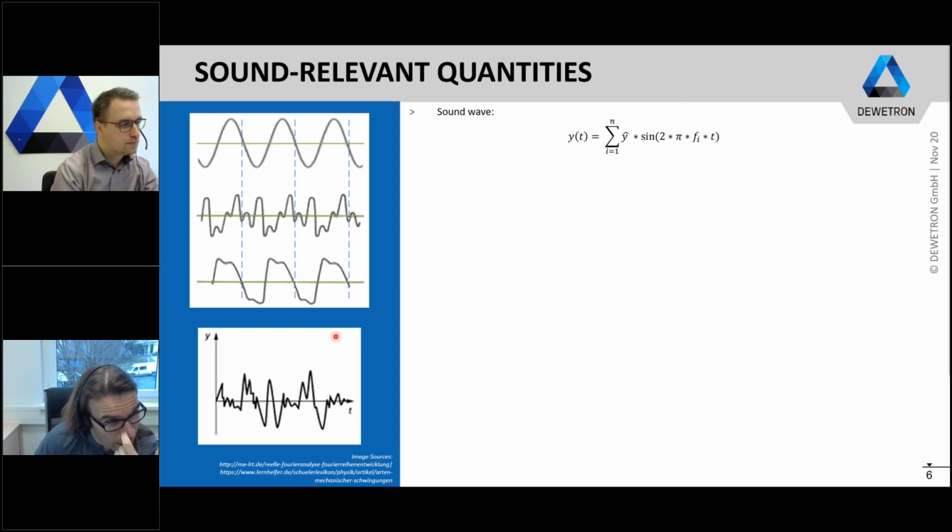And even if we have non-periodic sound waves, for example, like you see it here, like noise or anything else, we still could describe a non-periodic waveform with this formula here. We only have to make the exception that i is no integer here anymore, but that i can have values with decimals, so 1.37 or 1.58, 2 point anything. That's the only exception we have to make, and then we can describe more or less any sound wave or any sound signal with this equation here.